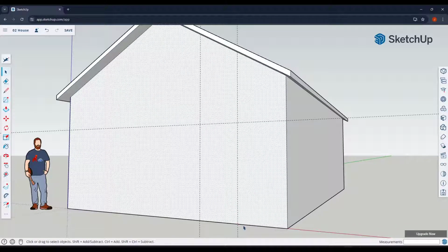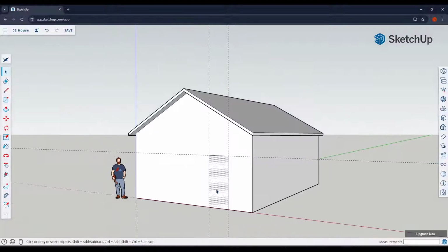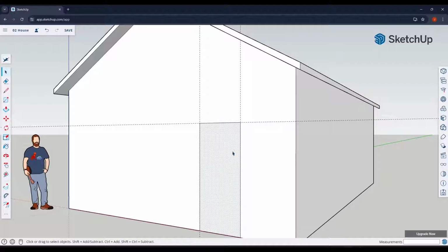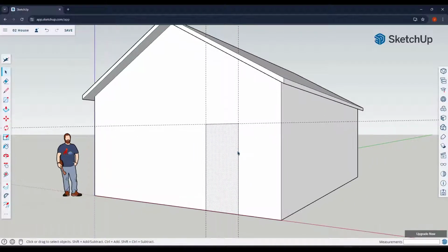And so in this situation, I want to draw a rectangle. So I'm going to tap the R key, single click, and move my mouse like this. Notice that creates door geometry that's separate from my wall geometry, like this. Now, in this situation, we're going to assume that our frame is going to be outside of this door leaf, not inside this door leaf. So I'm just going to tap the F key to offset this. And I'm going to offset this by a value of 2 inches right here.